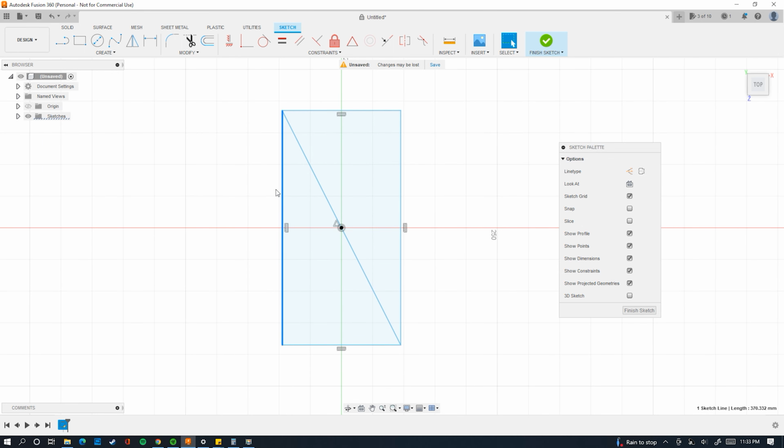When you're just starting out, this doesn't seem like a big deal, but it really is a core principle of this style of modeling. It's not just about putting some dimensions around that rectangle. It's about using the constraint relationships that you have the ability to define to reflect the nature of the geometry itself, where your model is going to be symmetric across the center line.